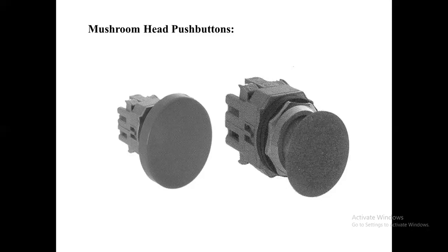It provides protection against the button being accidentally depressed by the palm of the hand or another object. It is therefore used in situations where pressing the switch accidentally could be potentially dangerous. Guarded push buttons are used in applications such as start, run, cycle, jog, or reset operations. For example, the reset push button on your computer is likely a guarded push button.